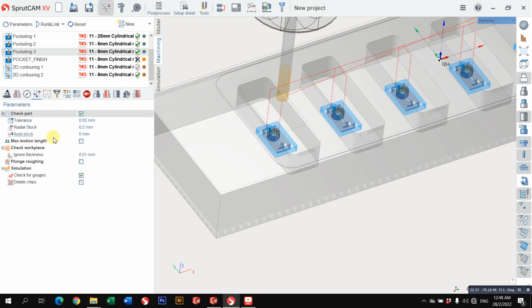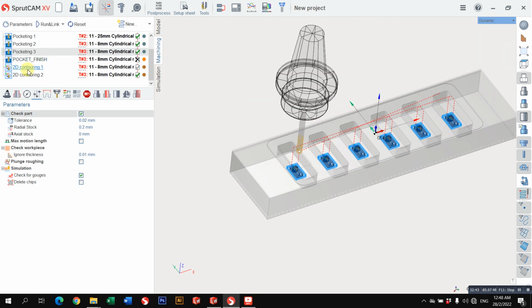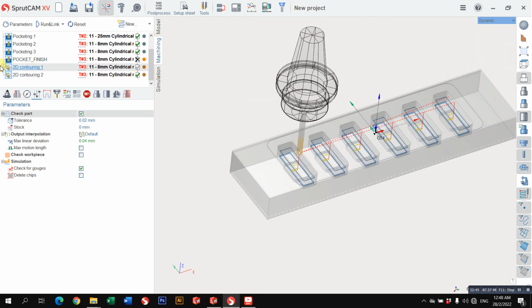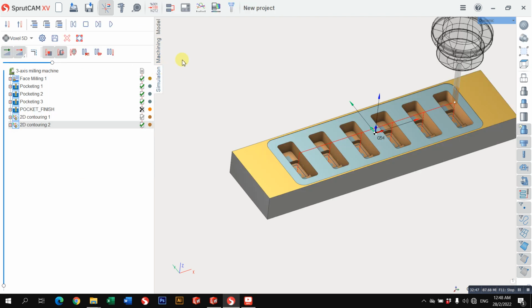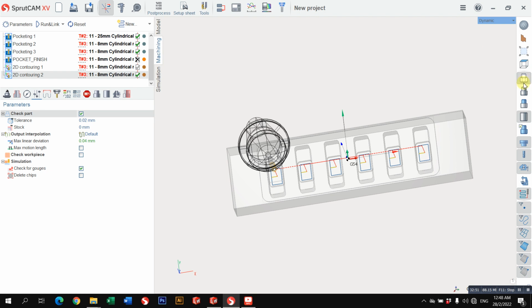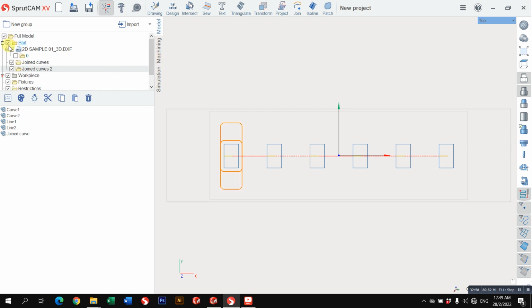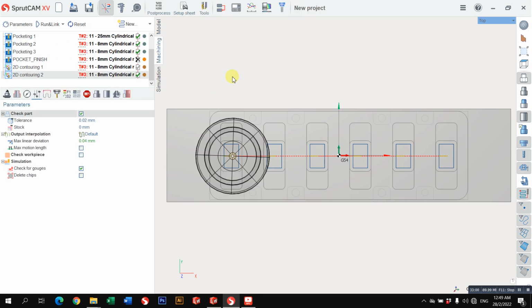Okay, let's say the first process will be a center drill, 6 mm center drill, 120-degree angle. Oh, this center drill is too long. We just like 80, working length like 10. Okay. So this one is tool number 5.